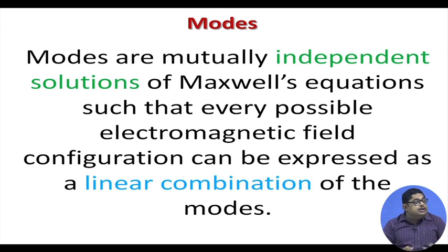Now, the precise definition of modes: modes are mutually independent solutions of Maxwell's equation, such that every possible electromagnetic field configuration can be expressed as a linear combination of the modes. So, for our learning purpose, if I understand the field distribution in a mode, then I can construct any signal. So, my model requires knowing what the field distribution of these modes will be.